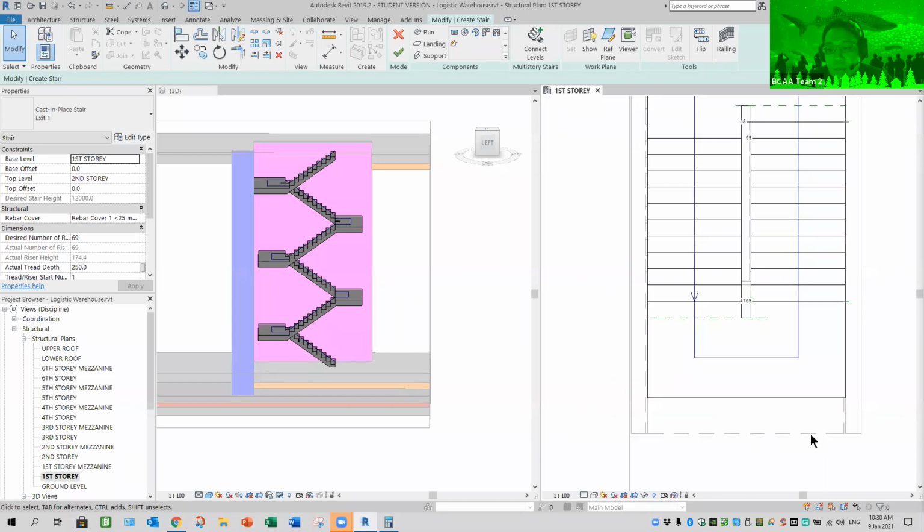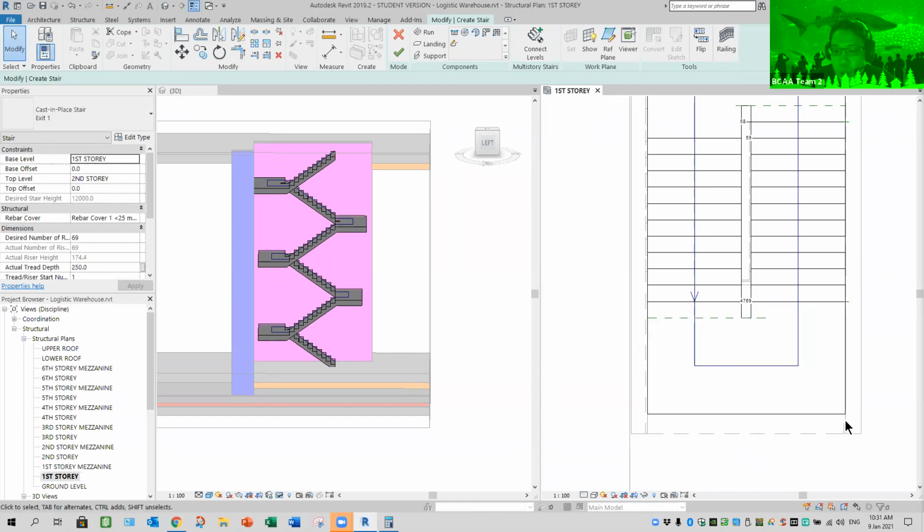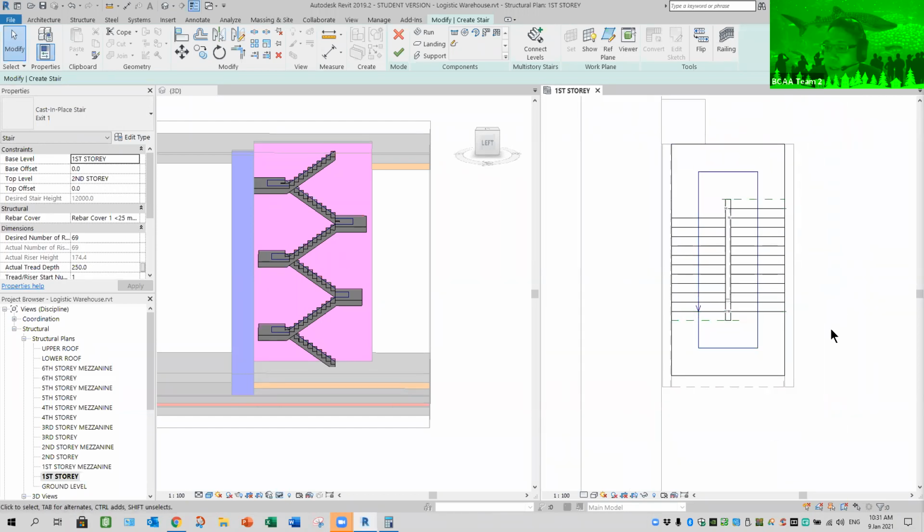All right, of course cannot be too far out, because here also have the curtain wall, so should be stopped somewhere. All right, so let me select this first, change the 1475. Yep, so this space is good enough for your curtain wall. So this is the staircase you should get like this. Any questions? If no, I'll stop recording, because the staircase is considered done for this.